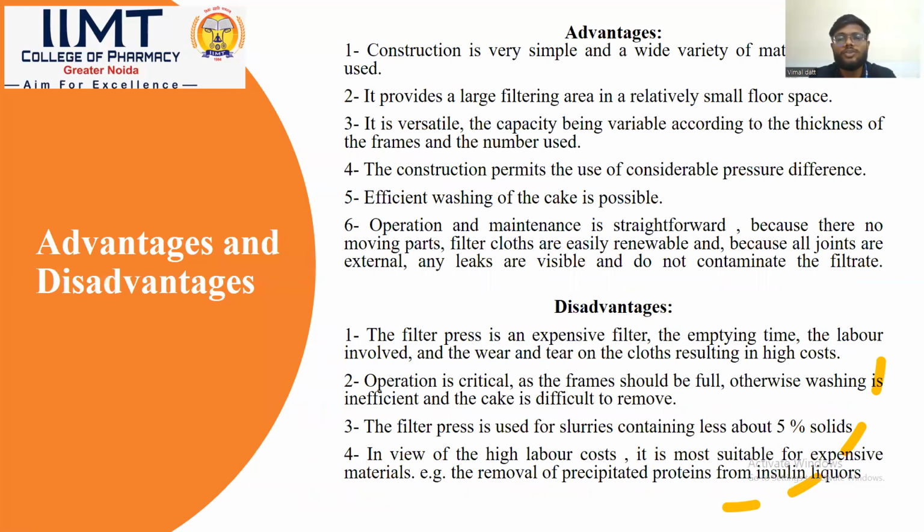Advantages: construction is very simple and a wide variety of materials can be filtered. It provides a large filtering area in a relatively small floor space. It is versatile, the capacity being variable according to the thickness of the frame and the number of plates used. The construction permits the use of considerable pressure difference. Efficient washing of the cake is possible.